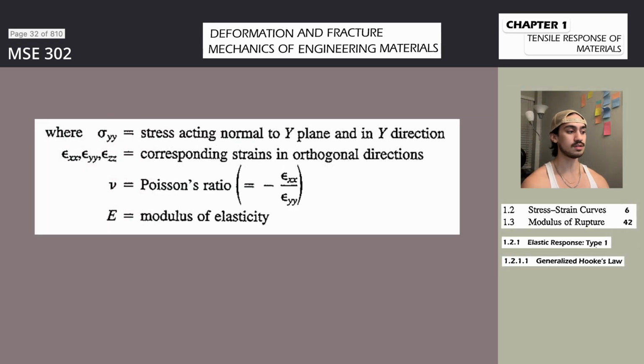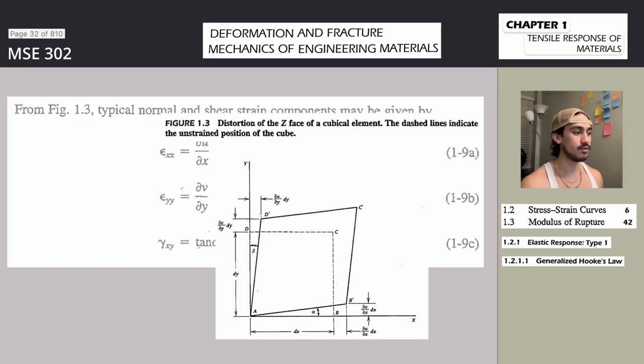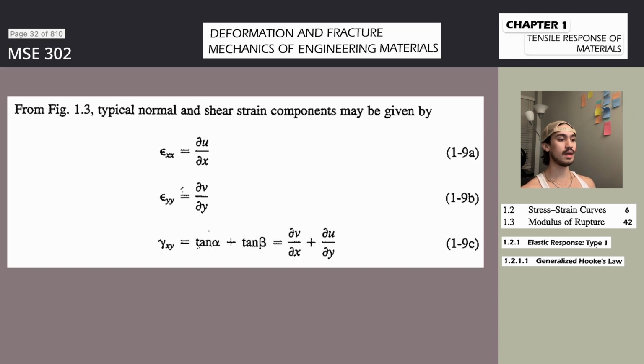The portion of the true stress-strain curve from the onset of yielding to the maximum load may be described empirically by the relationship generally attributed to Hollomon, Equation 1-20, where sigma is the true stress, epsilon is the true plastic strain, n is the strain hardening coefficient, and k is the material constant, defined as the true stress at a true strain of 1. However, Bulfinger proposed a similar parabolic relationship between stress and strain almost 200 years earlier.